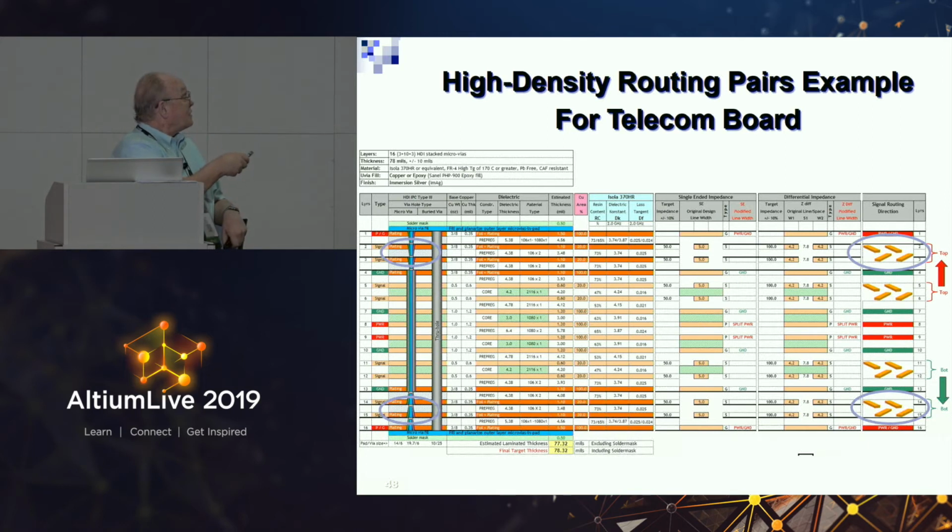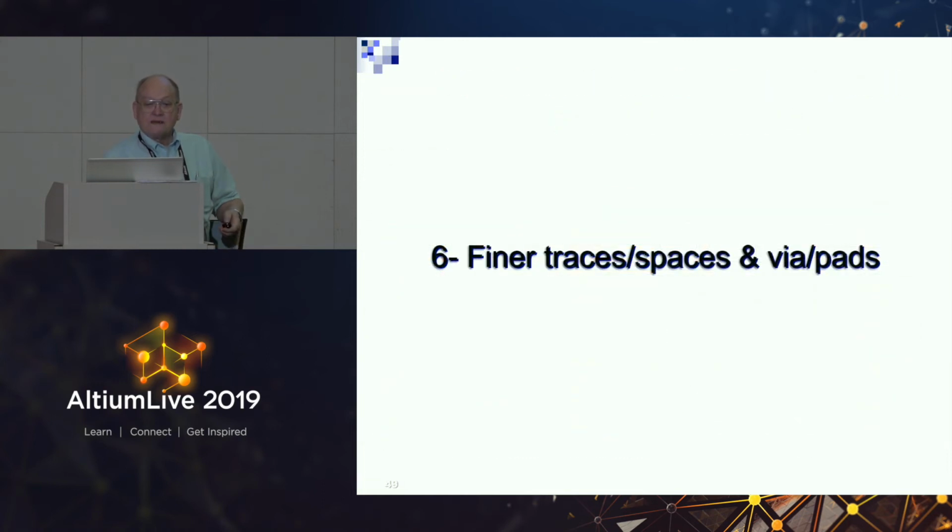And then these nets right here have much, much less sensitivity because they're influenced by these through holes. These two nets up here, they don't let a through hole anywhere near any of the sensitive traces because of noise coupling. So if you don't believe me, believe Cisco. They gave me permission to use one of their telecom boards as an example of taking HDI technology and using it in a proper fashion.